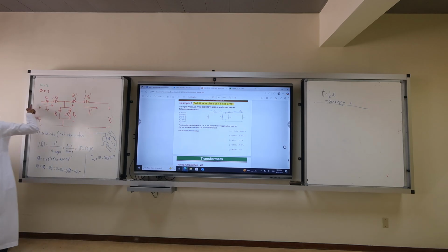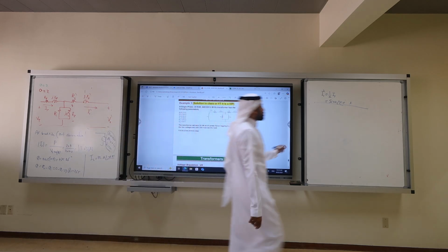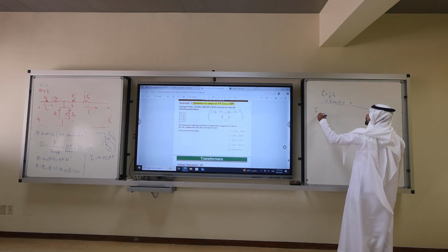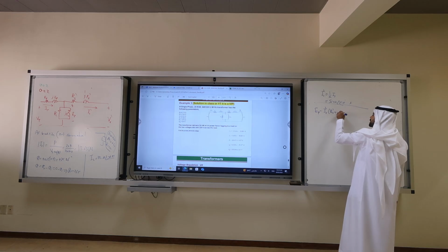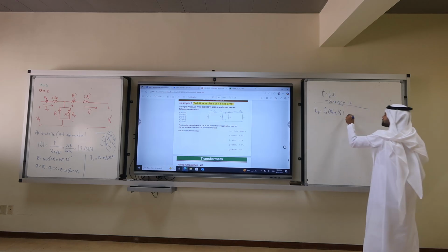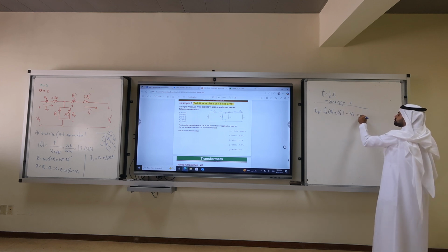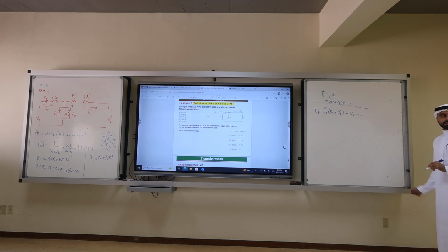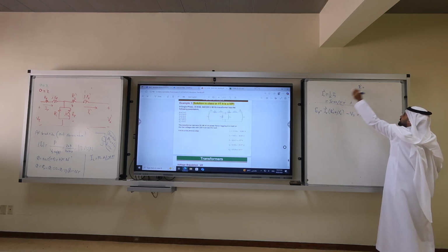In order for me to get Vp, I need Ip and Ep, correct? So let's get Ep first. KVL: voltage rise or voltage drop? Rise. Ep, rise, minus Is prime times Rs prime plus jXs prime, minus Vs prime, equals 0. What is Rs prime? It's written in the cell.